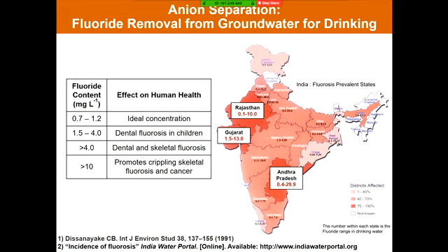The problem with existing membranes, like desalination membranes, is they may remove ions, but they remove most all the ions. They're not selective, for example, for lithium over sodium or fluoride over chloride. They show very low selectivity between ions of the same valence. And having those monovalent selective separation strategies would be very helpful for applications like this. Another one would be nitrate removal from agricultural runoff to prevent eutrophication, so-called algae blooms.